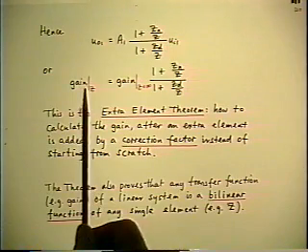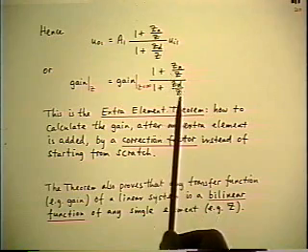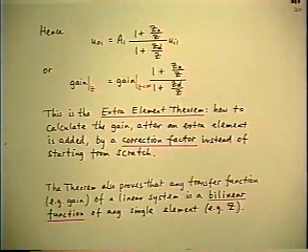So any transfer function of a linear system can be written as a bilinear function of any particular element in it. And the place where I found that talked about was in Bode's famous book, Network Analysis and Feedback Amplifier Design. And he derived it in order to prove this second statement.